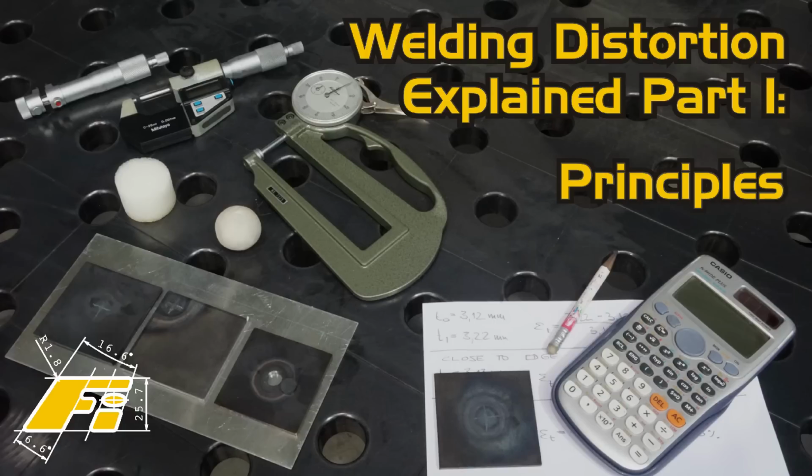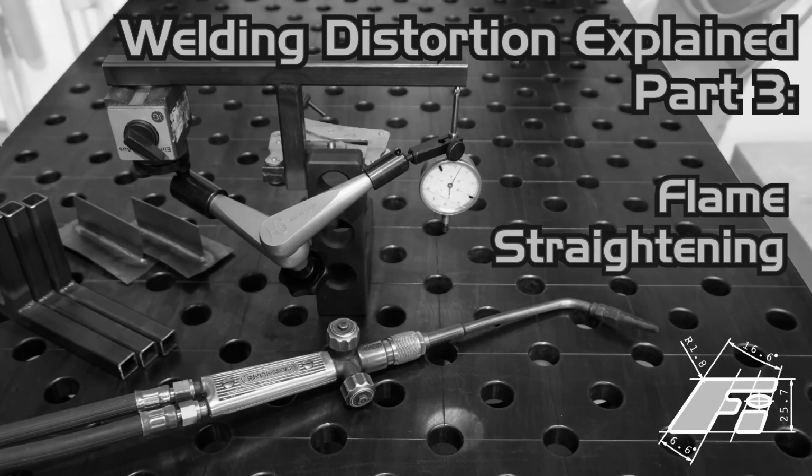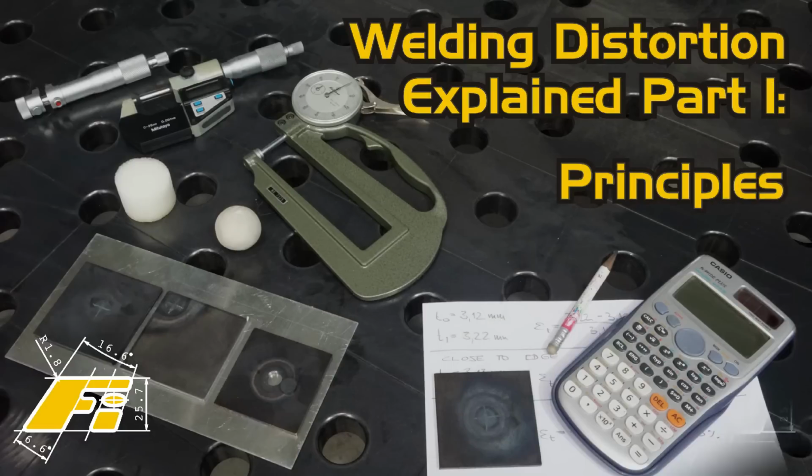Until now, no practical welding technique has been invented which brings forth distortion-free workpieces. And this includes the recent additive manufacturing techniques, since they are closely related to classical deposition welding. However, there are methods which allow us to influence and reduce welding distortion. Also, we can straighten welding distortion via the smart application of local heat, known as flame straightening. Both of these subjects are treated in the individual episodes of this video series.